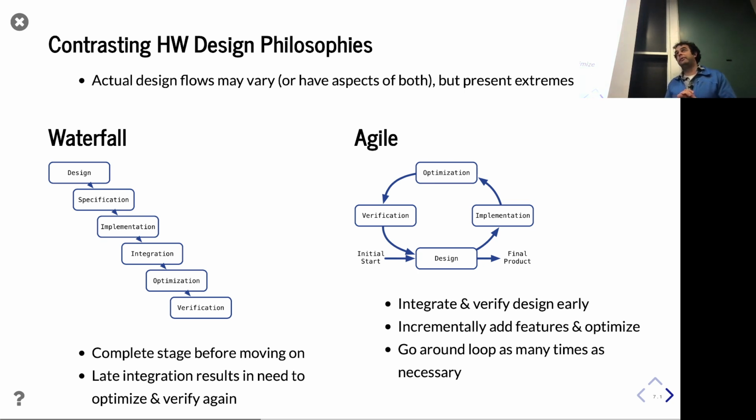So the kind of dream was, okay, what if I had a design, go from an RTL level design to a working GDS with pretty high confidence and have that be automated in a reasonable sense. They made some progress on that. You may have heard of something called the OpenROAD Project, which is now a newer DARPA program that's also trying to make this less human intervention, more automated. It's not all the way there. But OpenROAD's dream was, okay, given this design, could you have a working GDS in less than a day? That was kind of their metric. So a day is pretty long. But they're also doing the full physical design, not just a lightweight RTL testing kind of stuff.